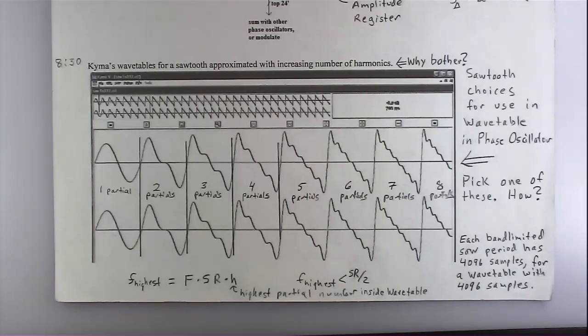Well, 24 times 1,000 hertz is the half sample rate. You don't want to hit that. So you can have up to 23 times 1,000 hertz, up to 23,000 hertz, right? So you have 1,000, 2,000, 3,000, 4,000, 5,000, 6,000, all the way up to 23,000 hertz. You don't want to have anything beyond that. Well, how many is that? So it's 1,000, that's 23.